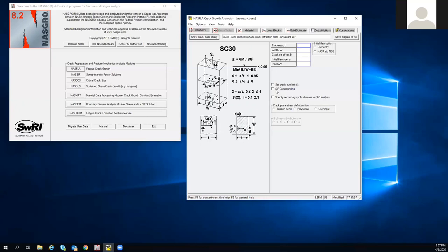That's more likely to have a flaw in it than, let's say, plate material or forged metal parts, which have much more process controls in place in order to make sure the manufacturing is repeatable and forms a nice polycrystalline material. So welds are very commonly generating surface flaws, and so that's why in most industrial applications, there are some forms of non-destructive evaluation like X-rays, dye-penetrant inspection, eddy current inspection,